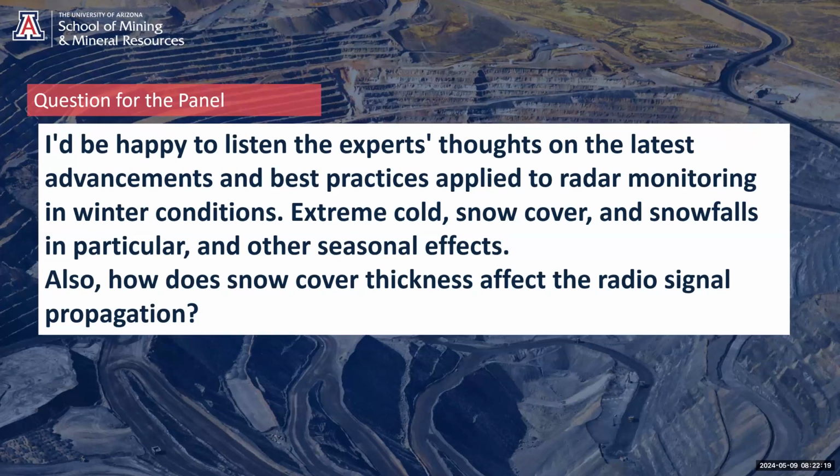And I try to focus on those little spots that are still giving you high quality information, even if the rest of the mine is covered with snow. That applies as well to defining the stable reference areas. So you have to try to avoid having them created on regions of the mine where snow accumulates, because that will be affecting the atmospheric correction. Snow accumulation or snow melting will end up having an influence in the atmospheric correction, so it could induce false displacements on the deformation maps and plots.